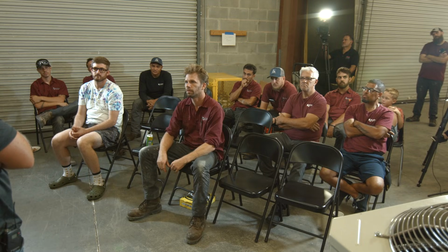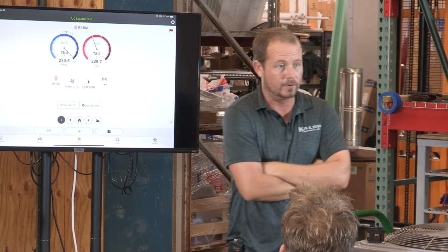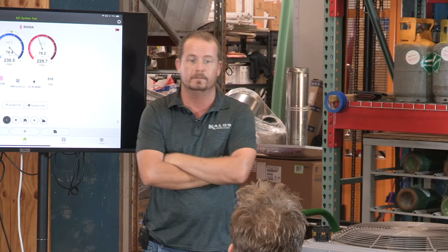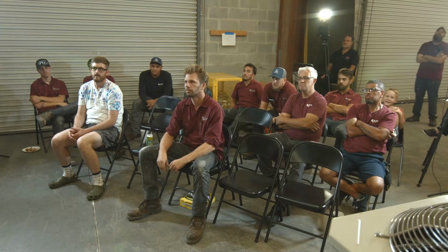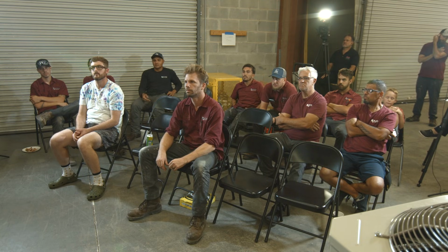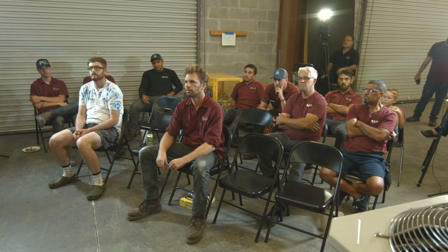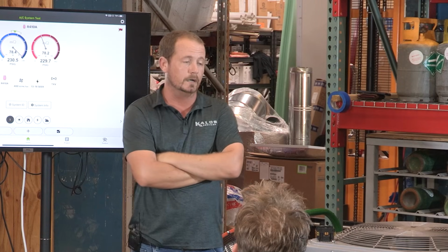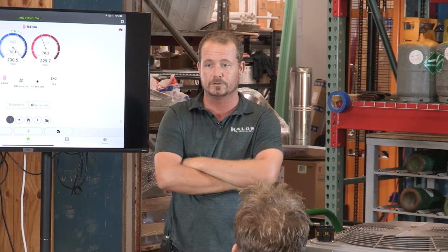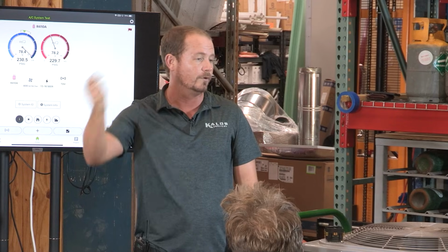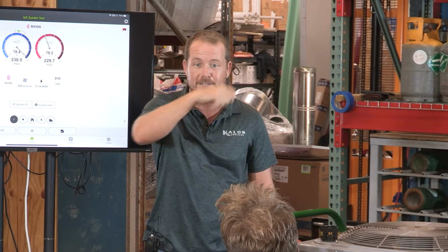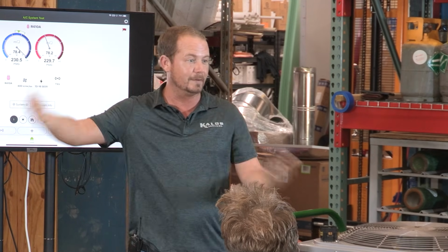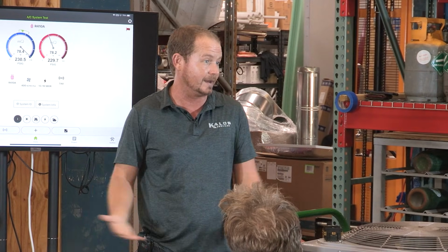You have to have a flow grid. You'd have to have some sort of a tool that measures flow, and there are a few. True Flow Grid is a really good one. What are some others? Anemometer. You could use a rotating vane anemometer, but your typical large vane anemometer is only going to go at the vents, so you'd have to go to every vent in the whole house, do a traverse on each one, which means you have to move it slowly across it, then time average it, and then multiply it by all of them. But even then, if you have duct leakage, that number's not going to be right.